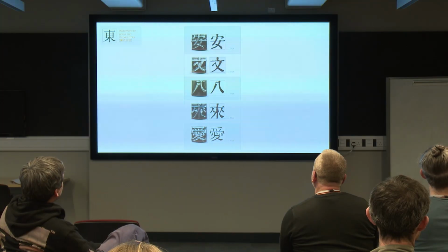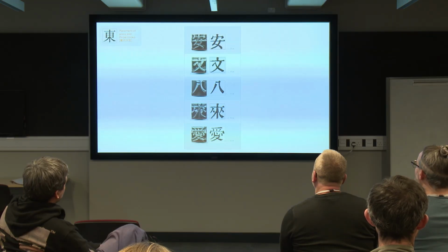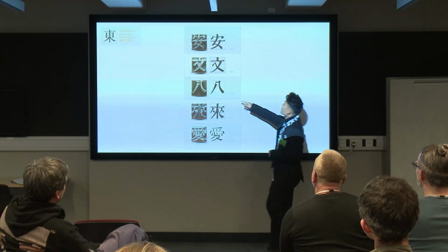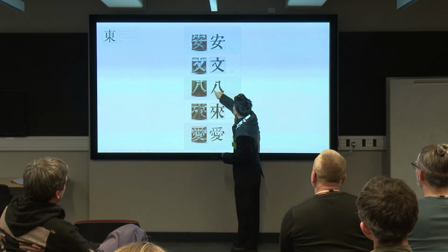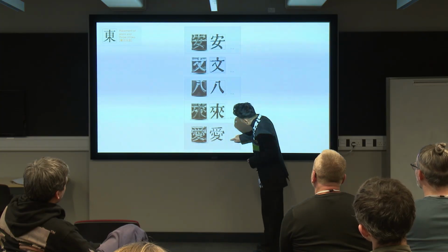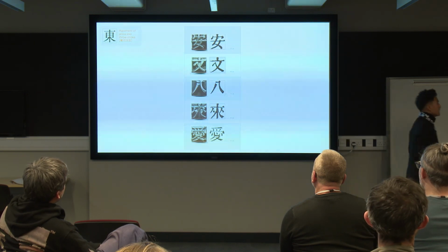So normally, the press stroke should be slightly higher than the fold stroke. This one is the fold stroke and this one is the press stroke. So it should be slightly higher. By measuring the difference, it should be slightly higher than it.